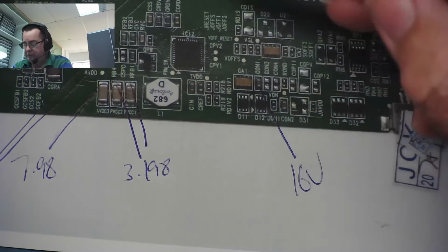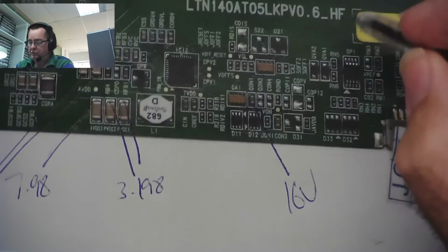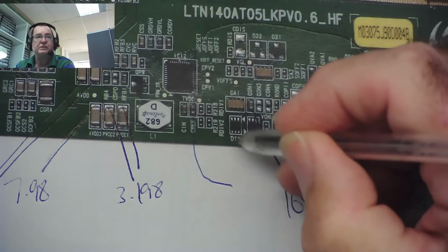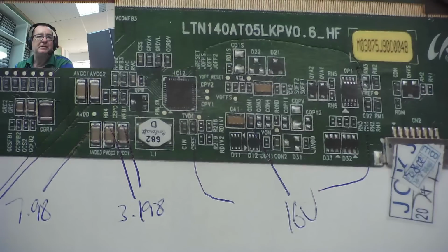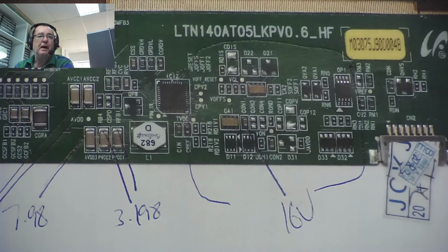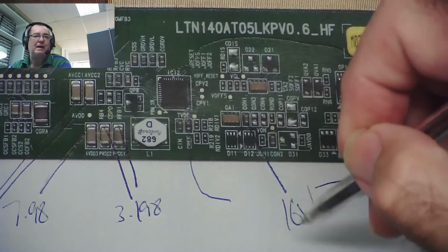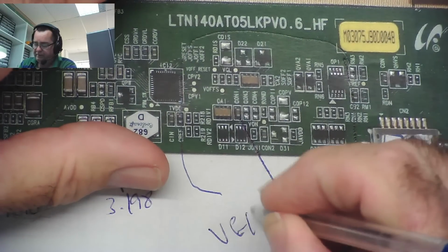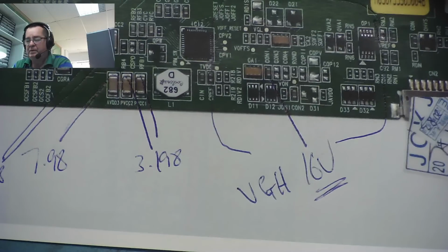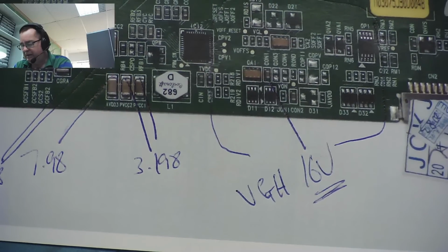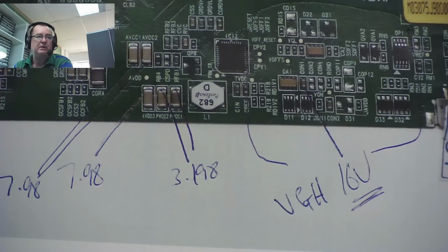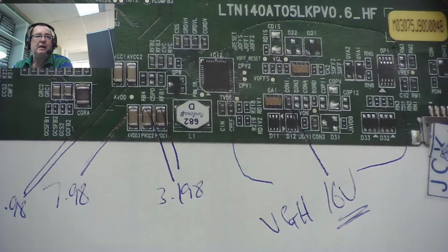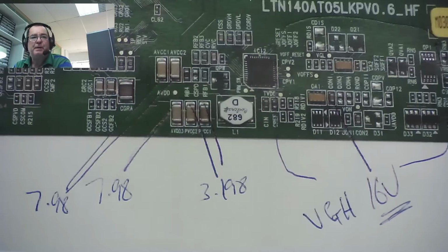Interestingly, now I looked around in this area where we thought this chip, this area, and these diode networks were probably similar to that circuit we can see in that little tutorial. And interestingly, on this capacitor I actually found 16 volts, which is the voltage we were looking for, VGH, if that information is correct. That was saying 10 for the AVDD, and we had 8, but it's in that region. And I found the 16 volts on here. That's the good news. The bad news is I found this on both panels.